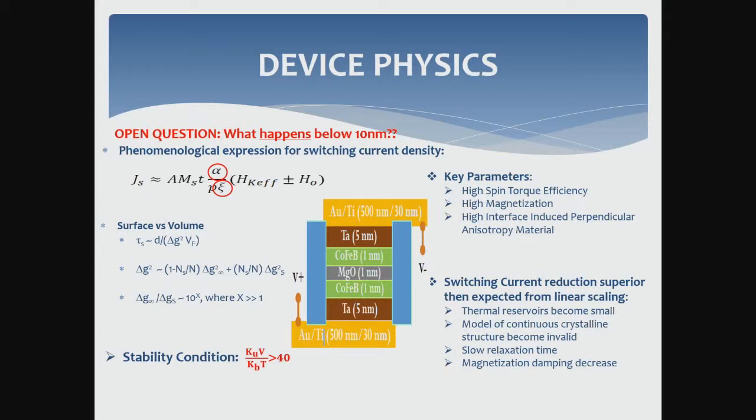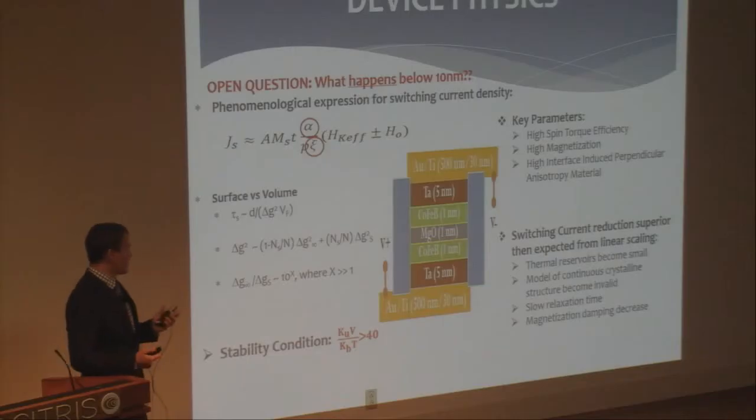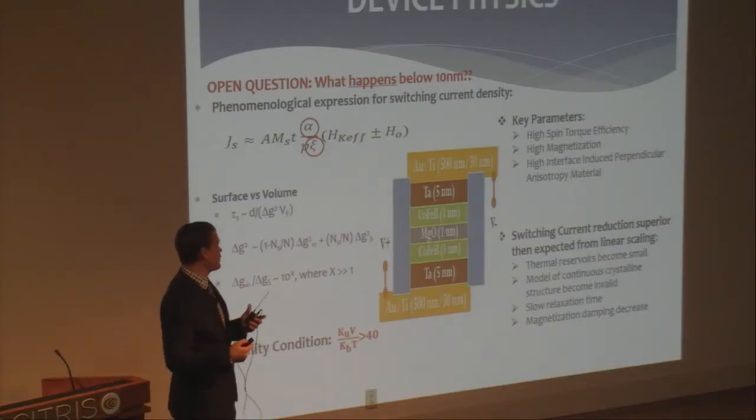So it has proper out-of-plane magnetization, which improves the spin torque efficiency factor, and of course allows us to have higher magnetization, which improves our signal-to-noise ratio when defining different states. So once again, these key parameters directly impact Xi, the spin efficiency factor, which facilitates the spin transfer torque effect.